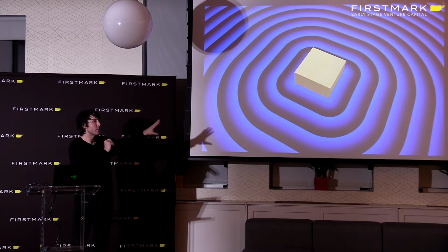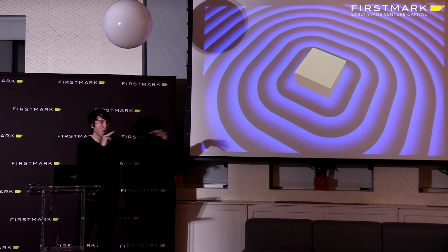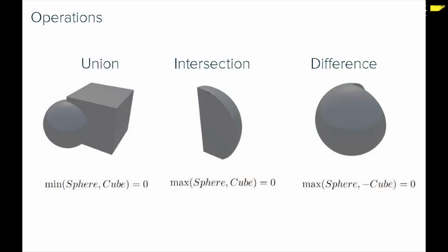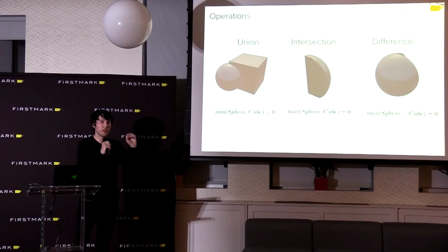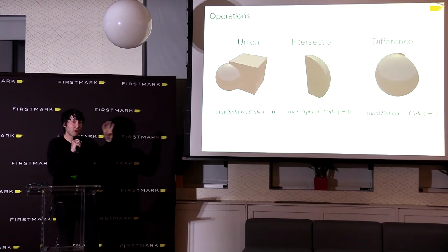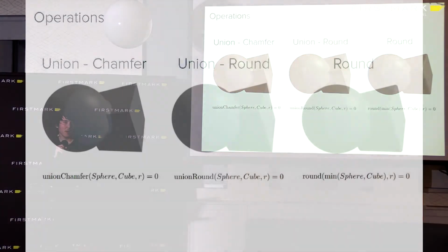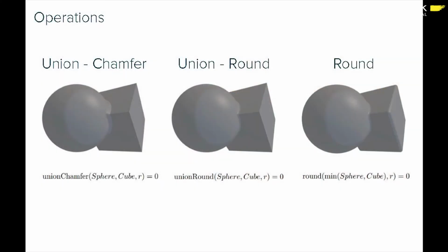And so again, we have this continuous smooth distance field in all of 3D space, and then we're just extracting that surface. The nice thing about working with these volumetric representations is that all of your standard CAD operations kind of come for free. In traditional CAD, Booleans are one of the most difficult things to do. In functional rep space, a union is just the min, intersection is max, difference is the max of one and the complement of the other. And you can also do things like adding chamfers, adding rounds, like traditional CAD. And again, these are all working on the volumetric function.